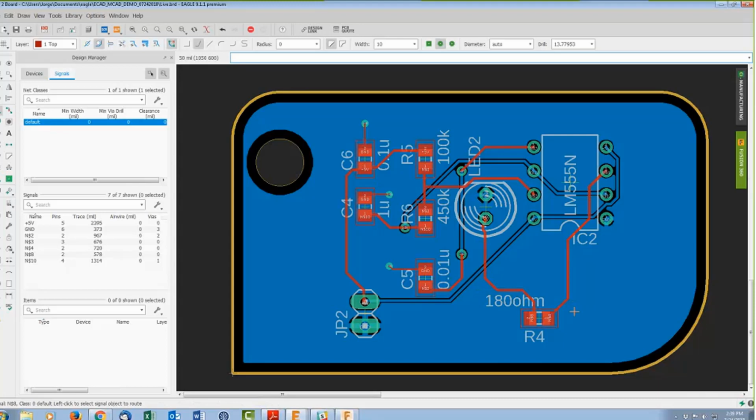I was going to ask you to use quick route magic to optimize that one. Yeah, we could also do that. Let's go ahead and see what quick route does. So quick route has a smooth signal function, which is really nice. It'll clean up any additional bends. And so if you just click on a trace, you'll see that it made it nice and straight. I can do the same thing here. Really, straightens it out, tries to minimize length. So now we can be happy with this.